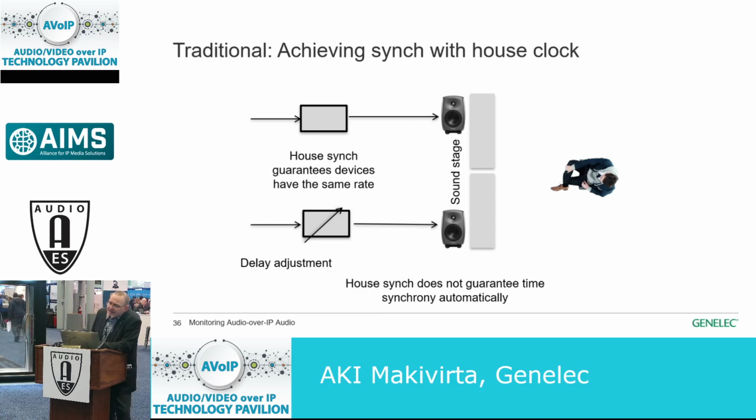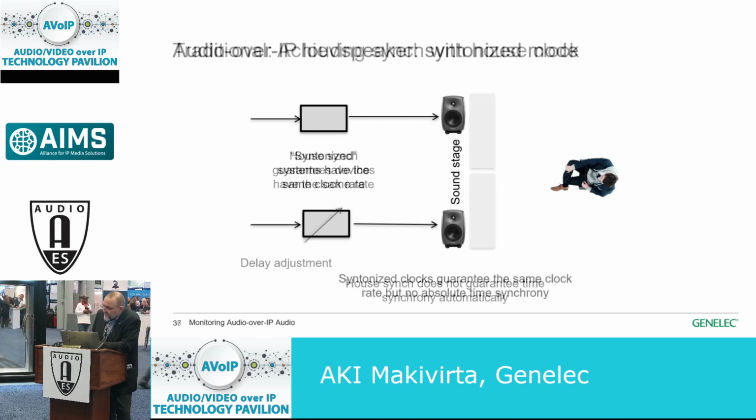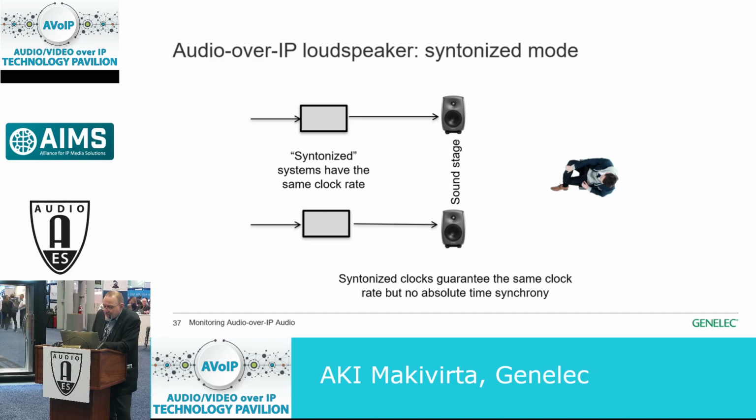The audio over IP standard actually has a similar notion implemented as part of, for example, AES67. They talk about the synchronized mode. The synchronized mode is working similar to the house clock. It doesn't guarantee you absolute time coherence, but it does guarantee that the sampling frequency is precisely the same in all devices.